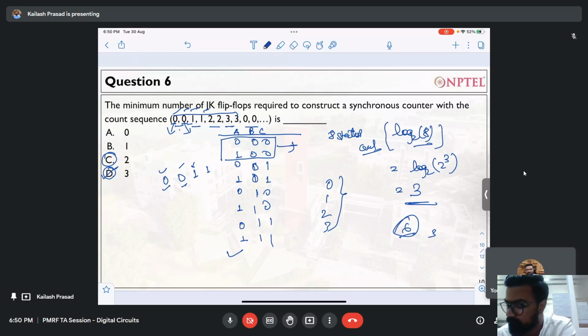Sir, while designing synchronous counters, any counter, we just make the present state and next state, and the inputs according to the present state and next state. Yes. Then for what inputs we get one, we make a truth table, and depending on what inputs are one, the input will be expressed according to the Qs, right?